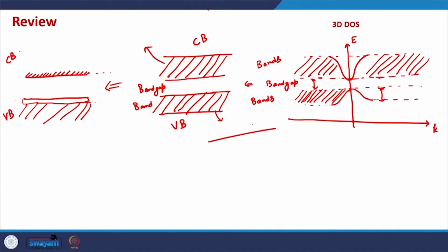We have already discussed that. From here we also saw that generally in a device the electron does not have a definite energy and a definite momentum value. That is why the electron in a device, or in a small region, cannot be described by a single wave function. So we need to take a bunch of wave functions corresponding to different energy values, and that becomes a wave packet, which is what actually describes the electron.